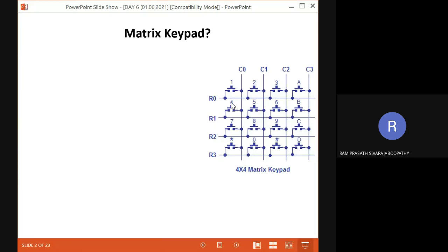When going for 4x3, 7 pins only. So whenever you are asked to have a matrix keypad, you have to think how many functional keys your keypad should have. You should make it a near perfect square. Exactly 16 in 4x4, and otherwise, bring it near to that. Both numbers must be more or less the same, and the pattern follows.